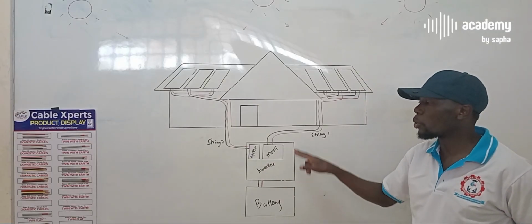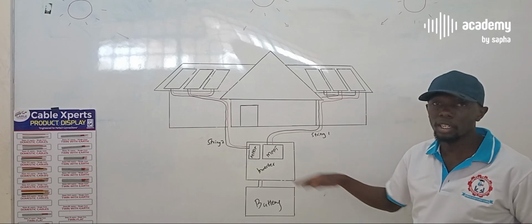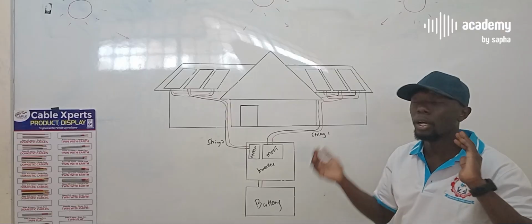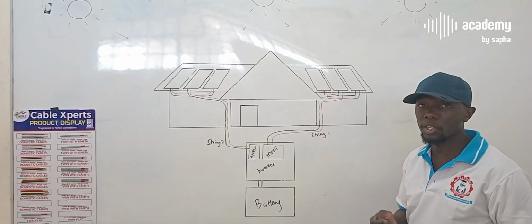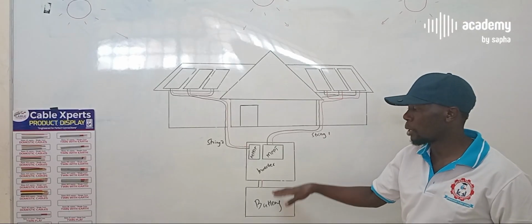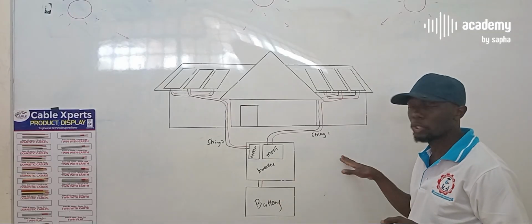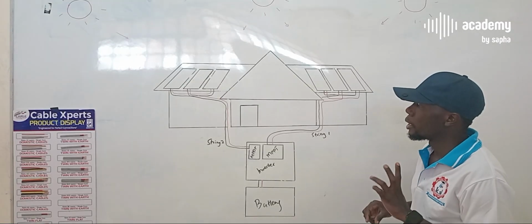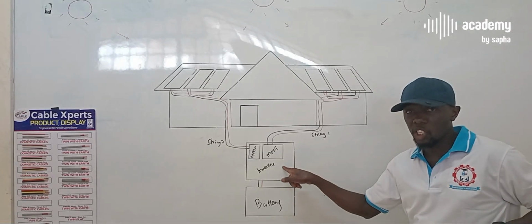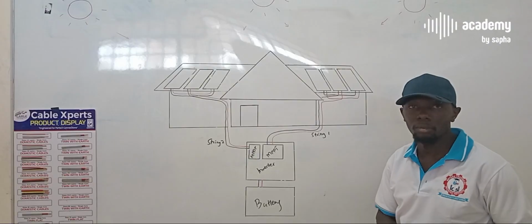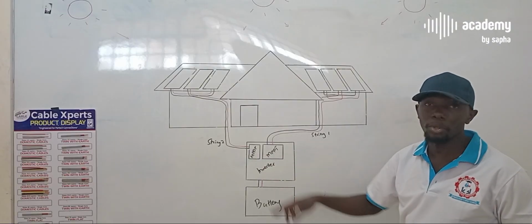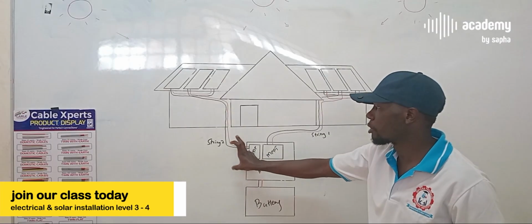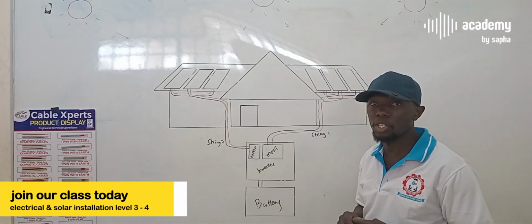Having two MPPTs, or three or even four, in the same inverter ensures that you can mount your panels on different sides of the roof, pull down the strings independently, and push power to your batteries or even to the loads optimally at any given time during the day. If you cannot get an inverter that has more than one MPPT, you can also modify your installation and have 3 or 4 MPPTs independently.